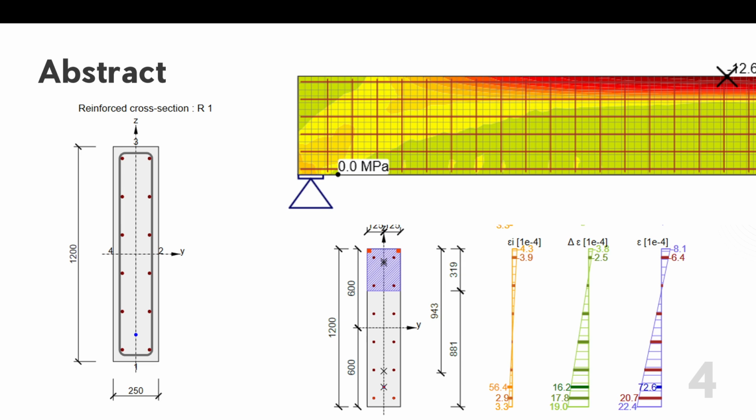Concrete and tendon stresses as the output will agree within 3%, while reinforcement stress diverges by up to 15%. I will talk later about why there are discrepancies, and I will show that this difference is not an error but a documented modeling choice.